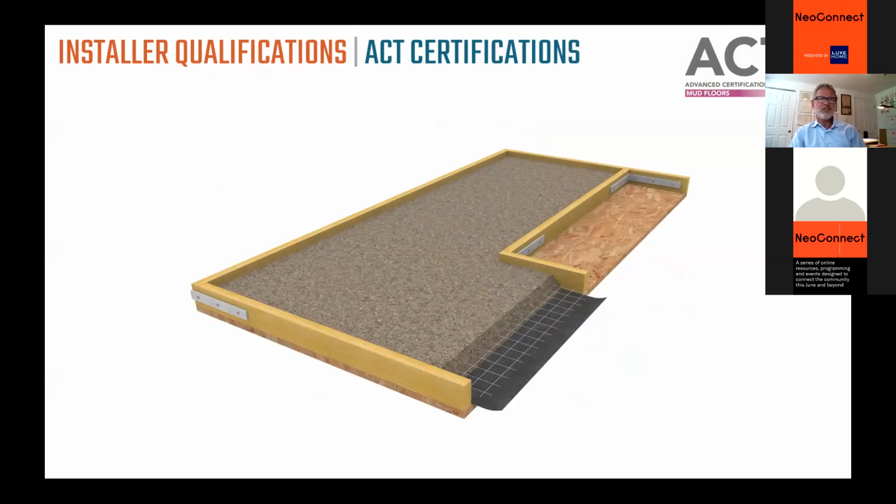Mud floors, this is essentially an exercise in floating a floor. It's very difficult to float a floor perfectly flat and perfectly level, but we're challenging them to do it here. Not only that, but is the wire reinforcement in the center 1/3 of the mortar bed? Is the cleavage membrane overlapped like it should be? Is the reinforcement overlapped like it should be?